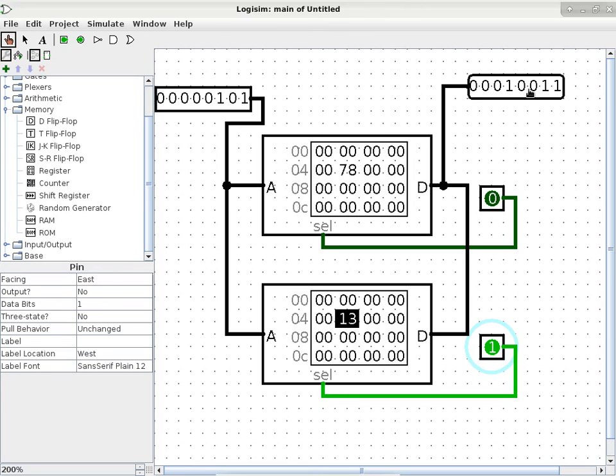Yep. Does the structure of the ROMs matter? What do you mean by structure? How they're arranged? Arranged, because the current reaches the top one first. No, the ordering does not matter, because this is really just logically displaying that we have the same wires going into both chips. So I can space them out, put them upside down, and whatnot. It would not really change the logical connection of these pins. They do not change by physically moving them around.